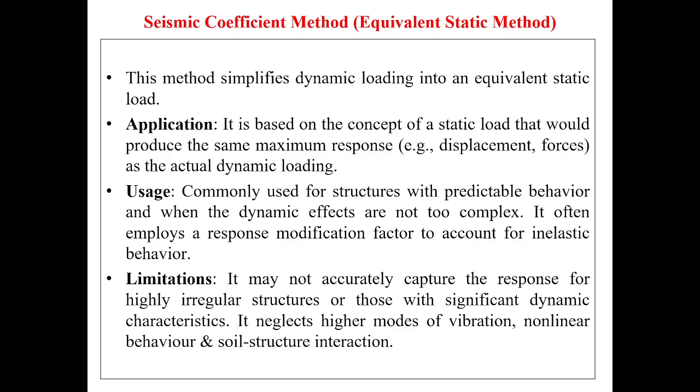So let us briefly see what the seismic coefficient method is. This method simplifies the dynamic loading into an equivalent static load. Now the application is, it is based on the concept of a static load that would produce the same maximum response, that is displacement and forces, as produced by the actual dynamic loading. Now the usage is, it's commonly used for structures with predictable behavior and when the dynamic effects are not very complex. It often employs a response modification factor to account for inelastic behavior of the structure.